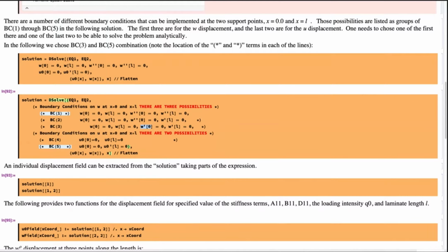You can use, not at the same time, but replacing, one end cantilever and one end free to also move, in which case moment will be 0 and strain will be 0 at that end.